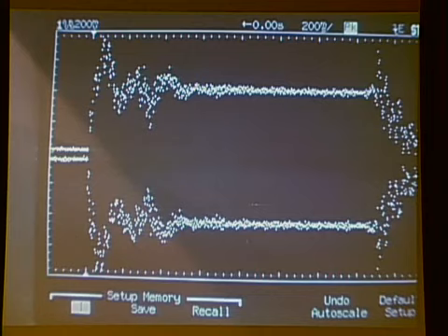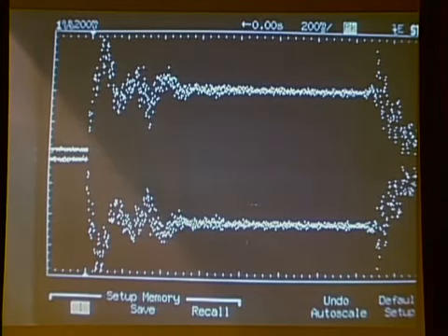We see a signal that is about 27 hertz. We've measured it, it's very close to 27 hertz. I therefore conclude that that must be the beat frequency between the 575 normal mode and the 548 hertz normal mode. That difference is 27 hertz. And you see that phenomenon, that beat phenomenon, obviously dies out. It is a transient.